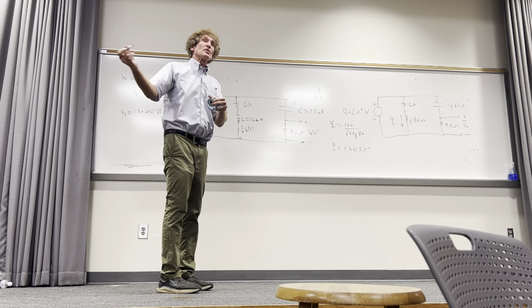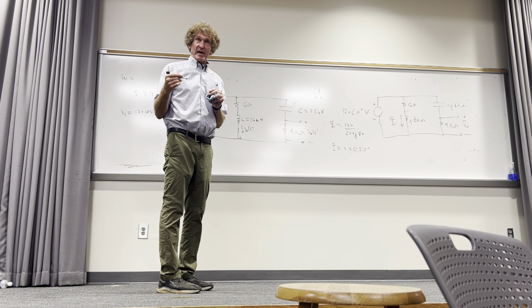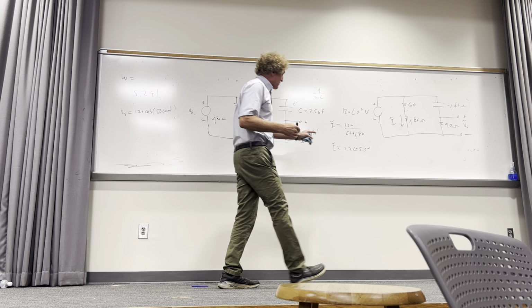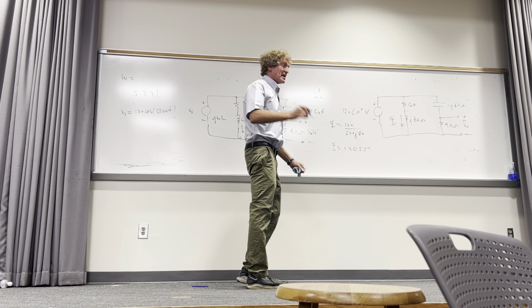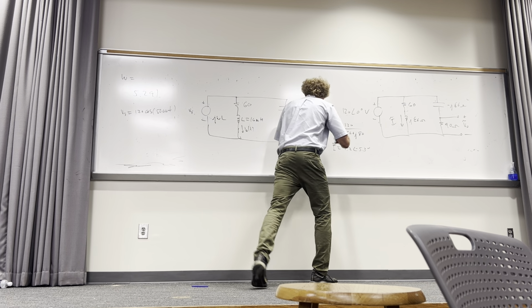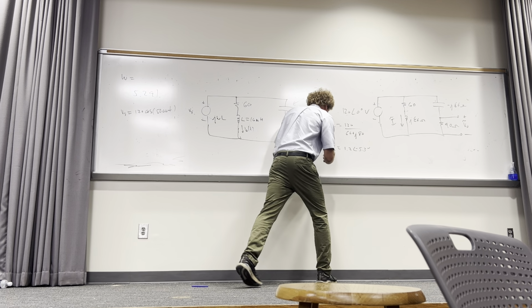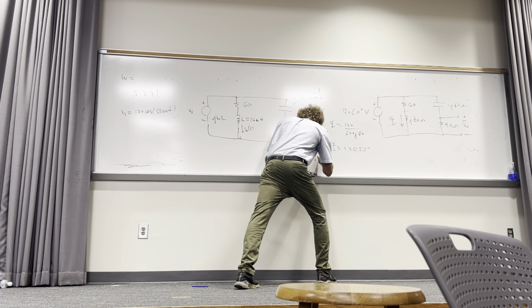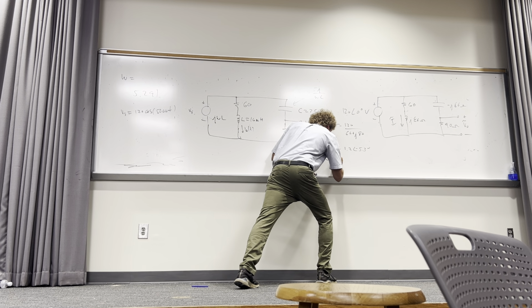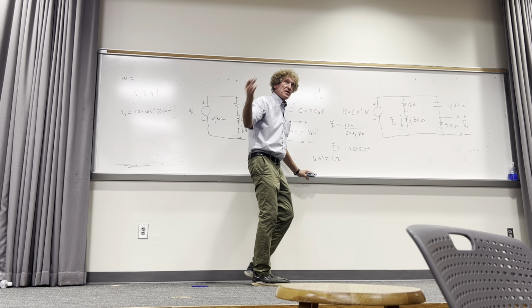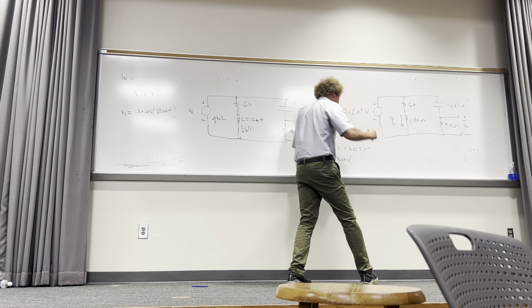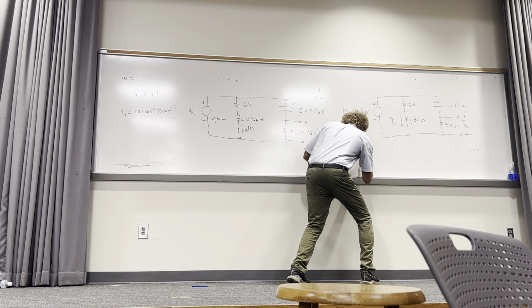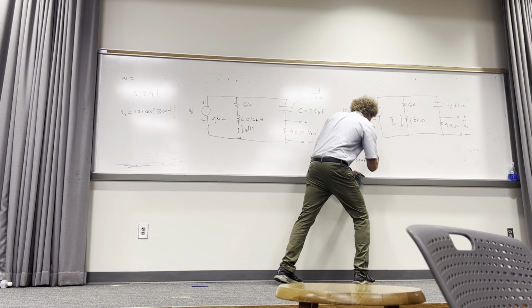All right? Now, I'm going to go right to the actual time domain next, so please be attentive. I have magnitude and angle in degrees, right? Now, I don't like doing it this way, but I'll show you. For the time domain, this I naught of t will be that magnitude, 1.2, then you put the cosine of omega t. Omega happens to be 5,000. And then you add the angle.